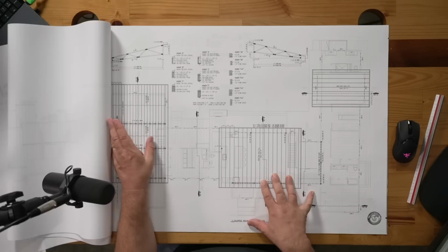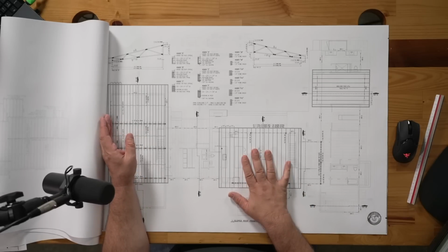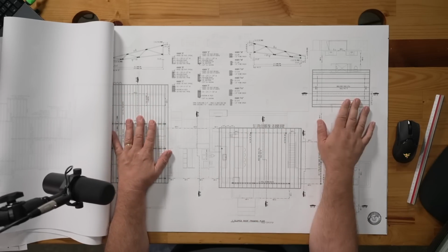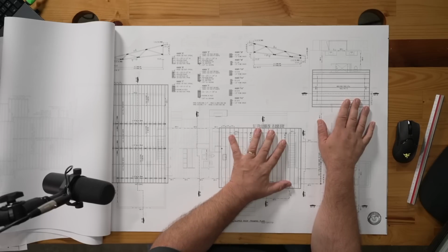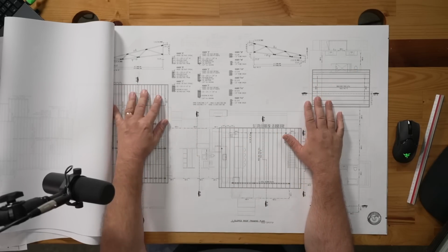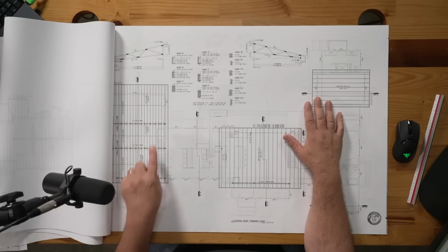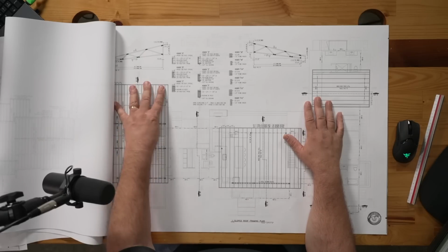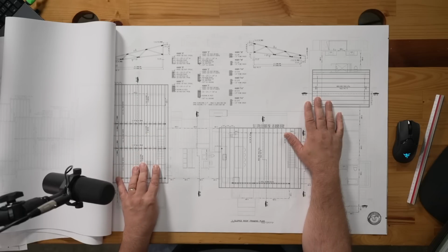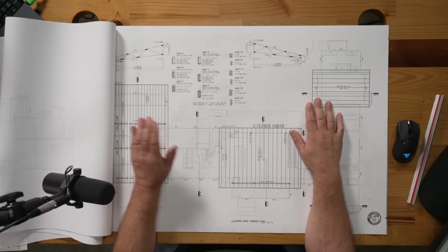This is the roof framing plan. You can see here these are all the sloped roofs. We have this one over the main area, this one over the owner's suite, and then this is the roof area over the garage. There's a couple of beams there. This one we chose to frame conventionally, so that's just a whole series of 2x12s, 16-inch on center.